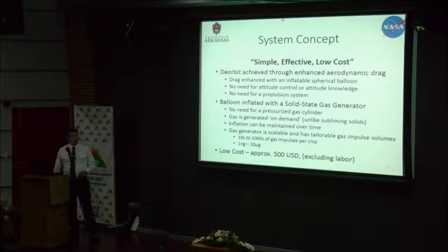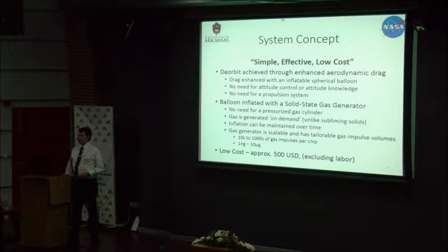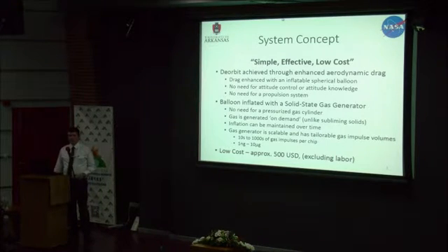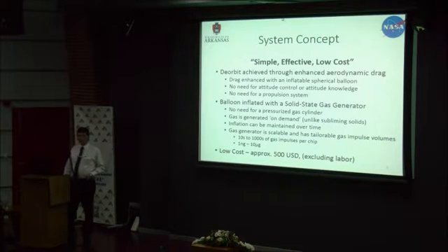The next step is we're going to use a solid-state gas generator to inflate the balloon. There's been balloons that have been flown in the past, but they use compressed gas in a cylinder, which needs a valve. You need compressed gas and a valve. Those are all things with failure mechanisms. So our solid-state gas generator will generate gas on demand without the need of any valves.